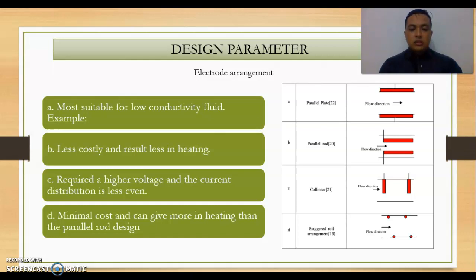So the electrodes can be positioned in the fluid stream or as a collar around a pipe, which provides a fully unrestricted flow channel. It is a better option for high conductivity, offering wider electrode spacing. However, the current distribution is less even, and areas of high current density found at the leading edge of the electrodes can produce localized boiling and arcing.